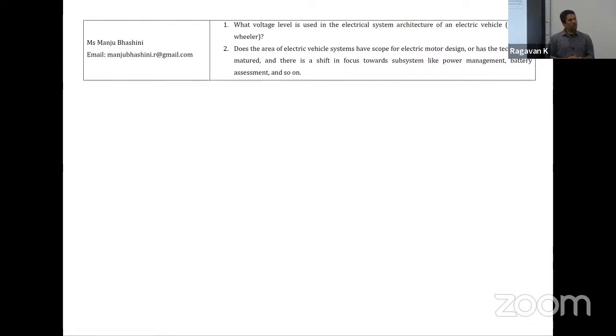But there are some people who are trying for medium voltage DC transmission. So medium voltage DC at 1.2 kilovolts with GaN devices. There is some work going on. I haven't seen anything commercial yet. I think 800 right now is the upper limit of where the DC link has kind of landed. And that's what we're talking about today. Yeah, correct, exactly. So that was correct.